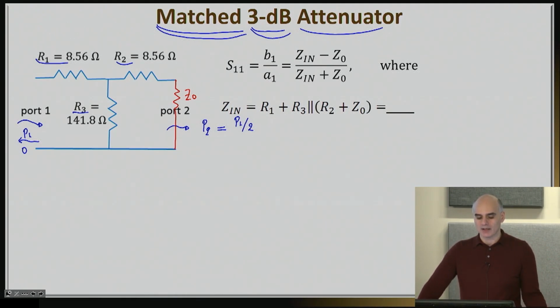I don't really see any ports, I don't really see any impedance. What is Z0? As we have discussed before, when you have a lumped element like this, the impedance Z0 is arbitrary. And so my advice in case of this question is to assume that Z0 is equal to 50 ohms and express your S parameters in a 50 ohm system impedance.